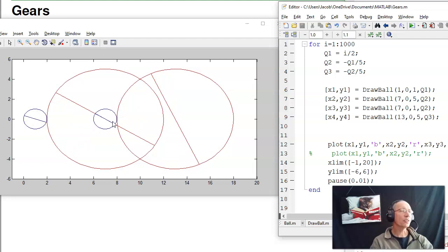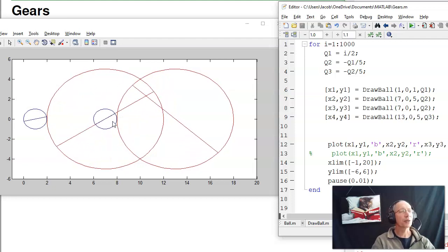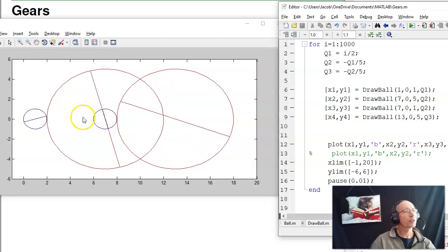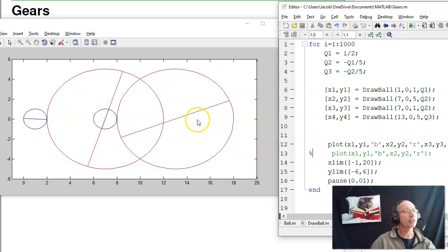It also changes the inertia, or the impedance going through the gear. For example, suppose this gear right here is really, really heavy, hard to turn. This one is small, it's really easy to turn. Energy is torque times speed. The energy over here, I've got a low speed, meaning really high torque. Over here, I've got to have the same energy. High speed, meaning really low torque. This one's easy to turn.